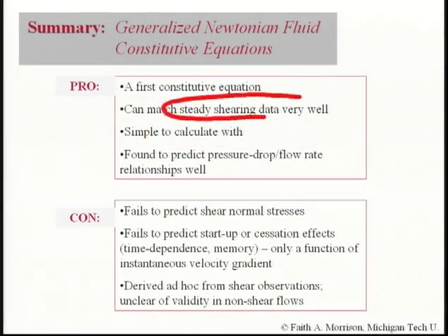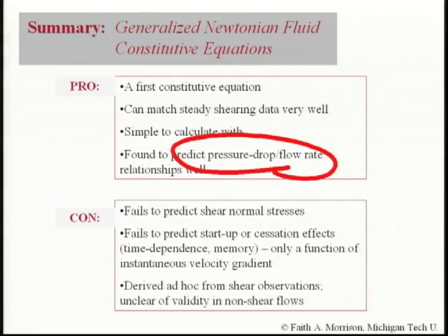If all you want to do is answer questions about steady shear flow, they're not bad either. So for instance, Julie King works with highly filled, carbon-filled plastic materials, and she's interested in just comparing the processing rheology of those materials. The power law model is perfectly fine for such a thing. Because what do you want that viscosity curve for? Is pressure drop flow rate. So that's going to be fine.